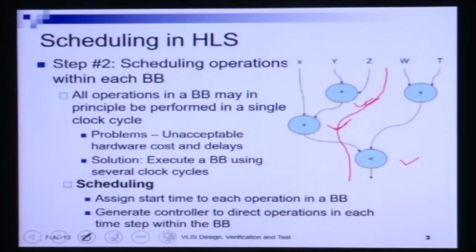So, what does scheduling do? It assigns a start time to each operation in a basic block, and it allows the generation of the controller, so that those operations can be directed at those time steps within the basic block.